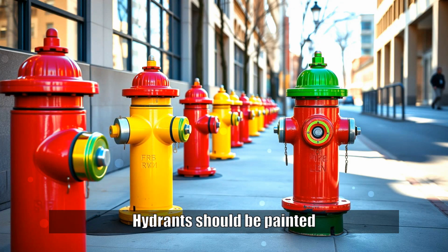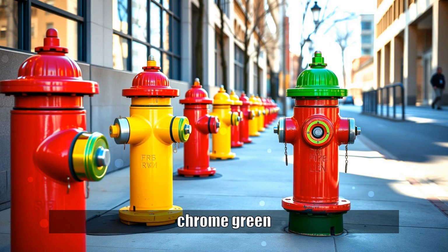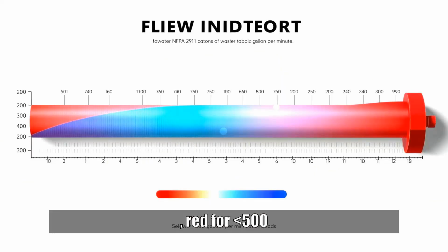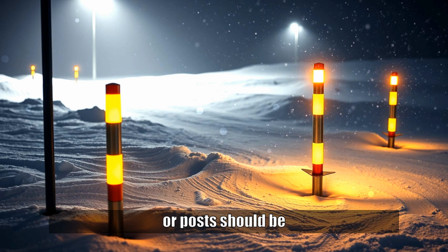Hydrants should be painted in reflective or bright colors, typically red, yellow, or chrome green. Outlet caps may be color-coded, red for less than 500 GPM, blue for greater than 1,500 GPM, per NFPA 291. Reflective markers, ground pucks, or posts should be installed in areas with low visibility, snow cover, or night operations.